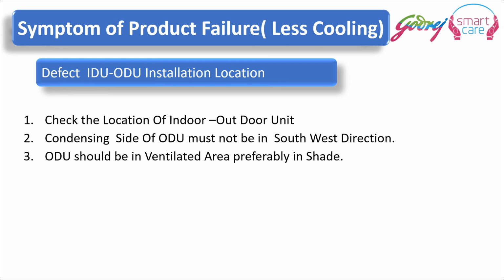If the defect is related to the IDU, ODU installation location, we have to check the location of the IDU, indoor unit, and outdoor unit. The condensing side of the ODU must not be in the southwest direction. The ODU should be in a ventilated area, preferably in the shade.